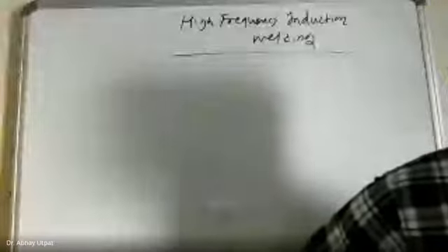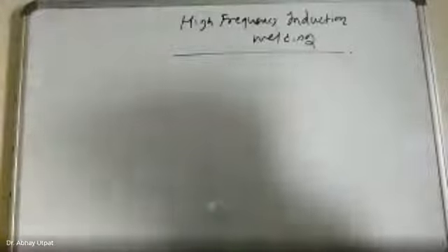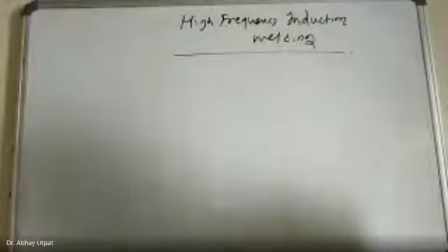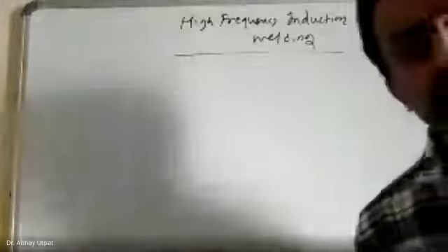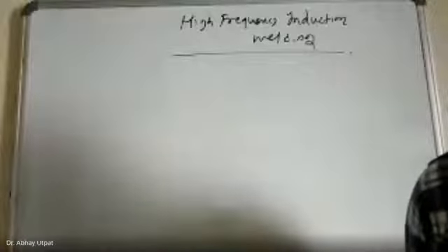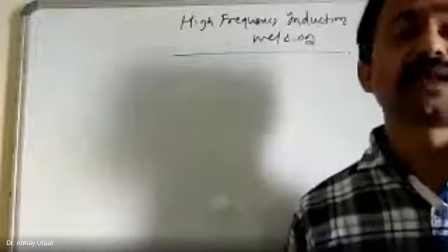Now, one of the important things: hermetic tight means airtight structures. You can produce a joint so strong that it will be airtight. It is called hermetic tight, and high pressure seals can be obtained from this process. Multiple joints can be welded in a single stroke, welded joints can be repaired also, and the rate of production is very high in this case.